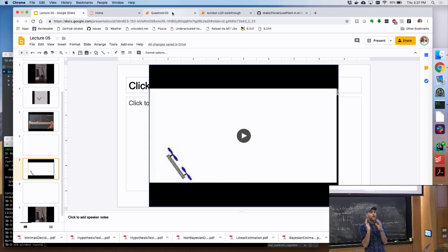And actually that's why quad rotors are great. I really think that is why quad rotors took off, because you write a tight enough little control loop, then control suddenly becomes easy. And they have enough control authority that the linear control works very well over a large regime. Okay, when you start getting into higher angles, faster speeds, then you get some more nonlinear effects.